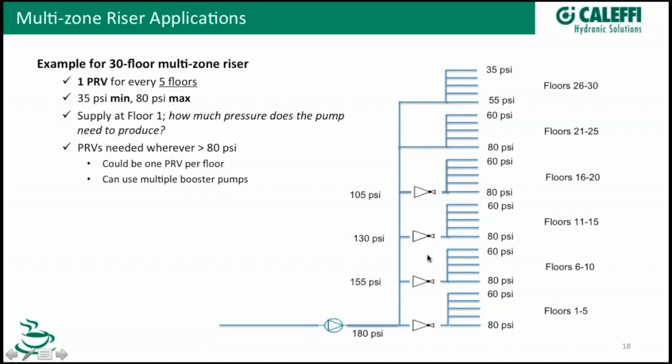Now, Bob talked about maximum flow. There are some manufacturers that only test so high. Higher pressure can also be a big issue. For example, when you're in the shower using those low flow, water saving shower heads, north of 80 psi is going to feel like you're getting an acupuncture treatment, and it might be a little uncomfortable. So it's not only to save your piping from erosion and corrosion and make sure all your fixtures work, but to make sure you're comfortable in the shower as well.